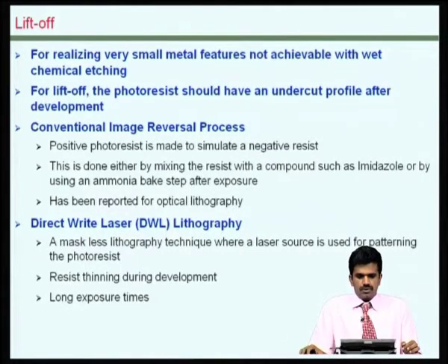So, in Liftoff we can have very fine resolution features by wet chemical processes. What is critical, as I mentioned, is that the dummy layer, the photoresist layer that you are using, should have an undercut profile after development, so that there will be a discontinuity between the top and bottom metal layers.